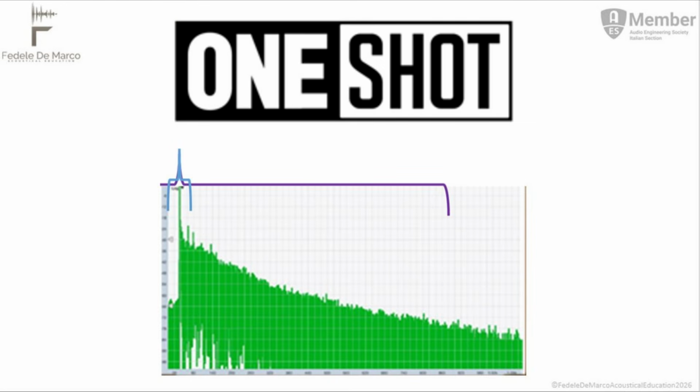For professional acoustic applications, which often involve long decay times, I do not use dual-channel FFT analyzers, and I do not want an IR that is merely the result of an inverse fast Fourier transform. My approach is to fire only once and directly capture the room impulse response in the time domain. This allows me to transform it using Fourier, Hadamard, or other methods, freely choosing the windows and the time span I require. This is a different path, better suited for interdisciplinary work and more compliant with specific standards.